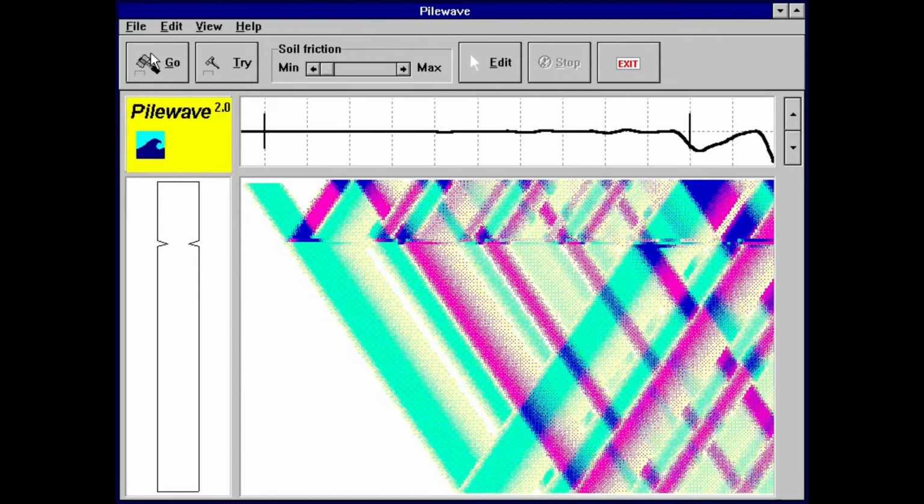If you're doing this, particularly in a pile integrity test, a PIT or something like that, you're actually returning the stress waves to the top. You can determine where defects like this are based upon the return pattern.